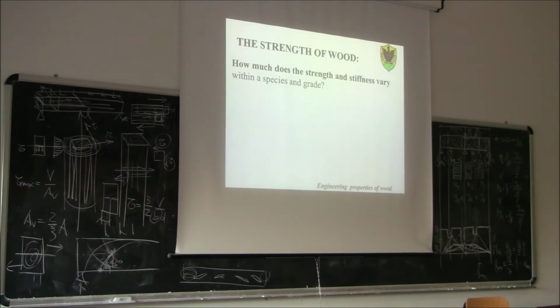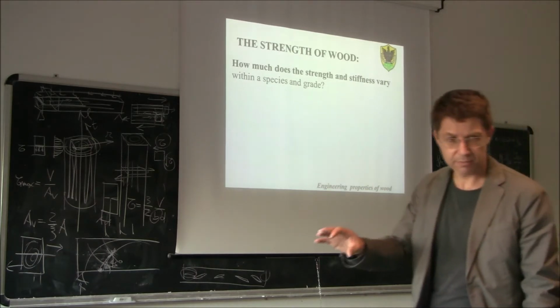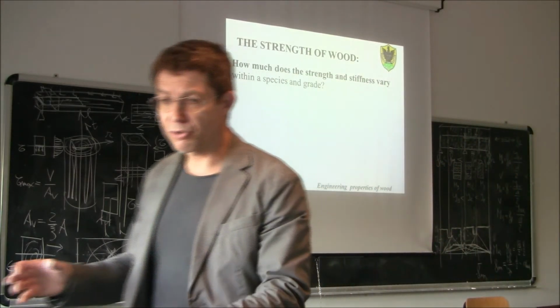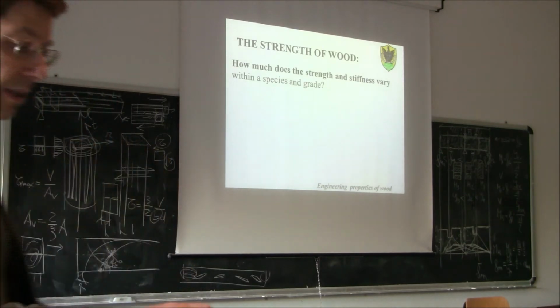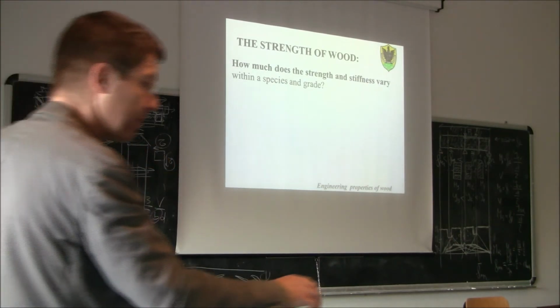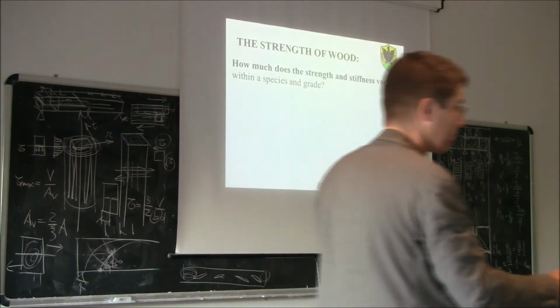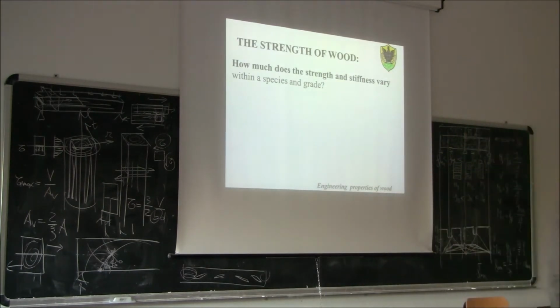Nowadays, all the timber that we can use in structural design should be classified. The actual name is grading. So when we talk about timber, we talk about grading of timber, which means assigning the timber to a certain strength class. It also means that your timber must arrive at the building site with a stamp showing the strength class and some well-defined properties.